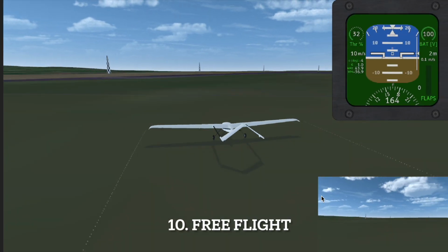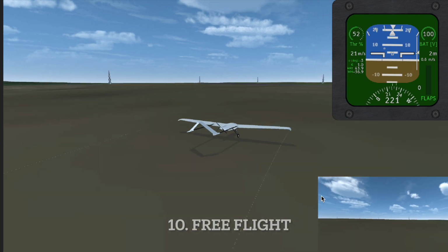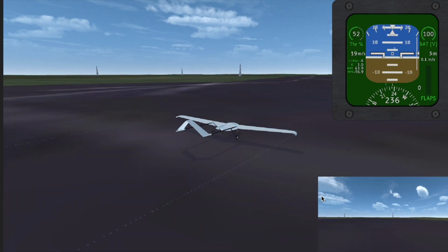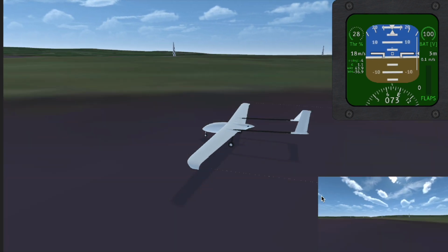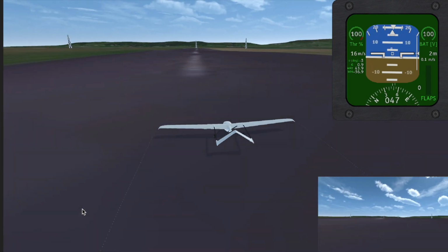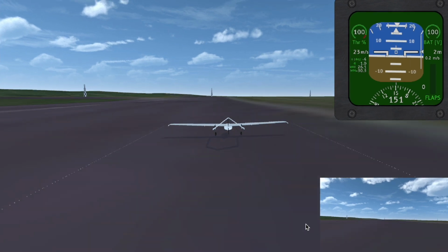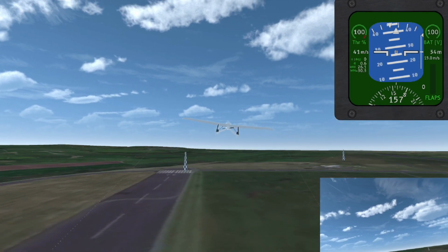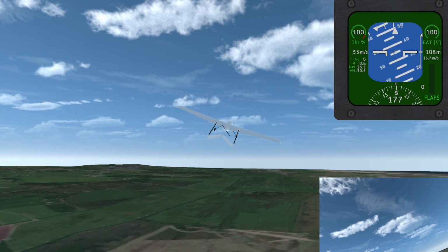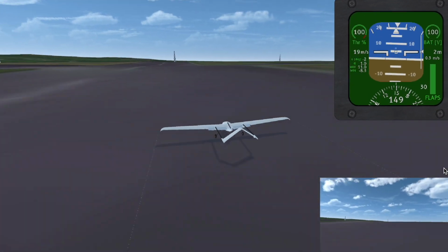The steering and rudder input offer enough authority for maneuvering the Albatros on the ground, but high-speed steering can increase the risk of the wings touching the ground and place significant force on the nose gear, potentially leading to failure. The minimum speed required to lift off is 39 m/s without flaps and 27 m/s with flaps deployed, which is considerably higher than the predicted stall speed.